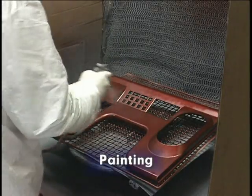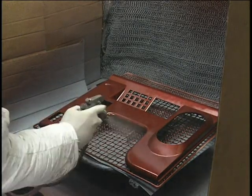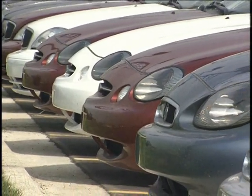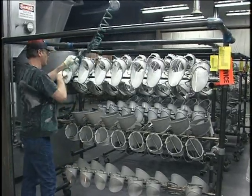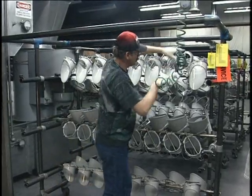Liquid paints may be applied to plastic parts for many reasons, but usually to ensure proper color matching between adjacent plastic and non-plastic parts, as on an automobile. As with any finishing process, surface or substrate preparation is a critical step. Surfaces must be absolutely clean and free of any contaminants. This helps ensure adequate paint adhesion to the plastic part.